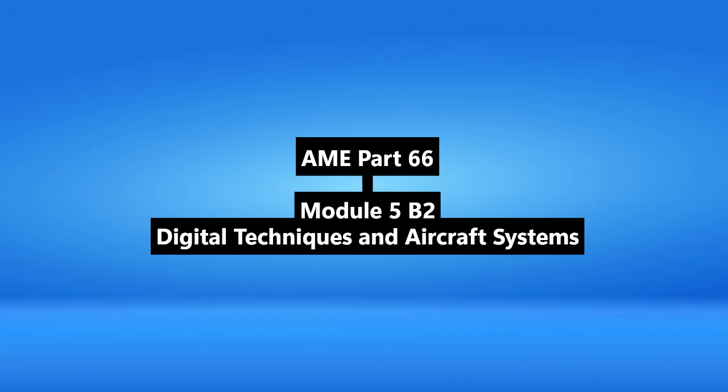Can you give an example of a microcomputer system in an aircraft context? Sure. A classic example is the flight management computer, the FMC. That's a dedicated computer managing the flight plan, performance calculations, fuel predictions, all that. Its peripherals would be things like the cockpit displays, where you see the route, the CDU, control and display unit, the keyboard and screen the pilots use to interact with it, and maybe a data transfer system for loading navigation databases or software updates.